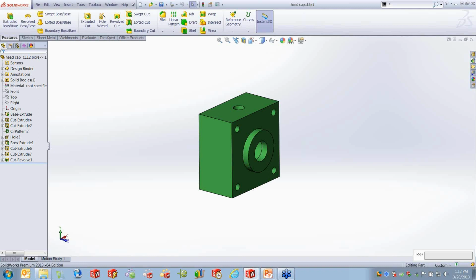Question about textured threads or cosmetic threads. When you look at the hierarchy of what's faster than what, no threads is going to be the fastest, right? No image, no threads. Cosmetic threads is going to be the next one, where you actually do the image on there. That's going to be the second quickest way, but there is a slight hit. Not much, but if you're talking 10,000 components, do you really need to see that at the upper level?